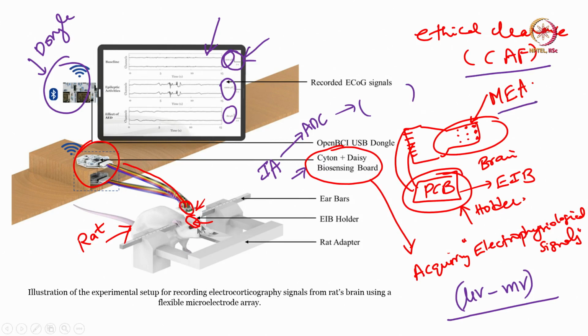Then you need to have this microelectrode array, then from the microelectrode array the signals will go to this system, the biopotential acquisition system. From this system the signals are converted to digital, and then they are sent to the software GUI, and here the signals will be stored in a .txt file or whatever file format it is compatible with.